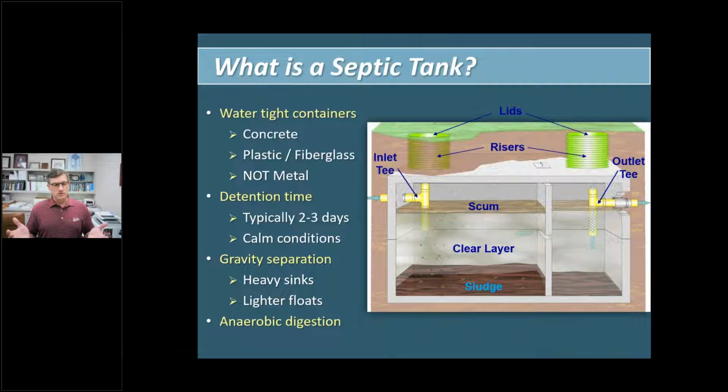They're just a much larger volume, but they will also have a time frame. So when we think about lagoon systems, we may be thinking about a 30 to 45 day life cycle. So you want to be able to hold 45 days of water that may be produced within your customer base. Because again, there's a time frame of natural treatment that we may see in there.